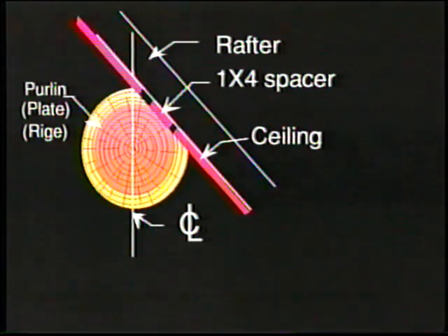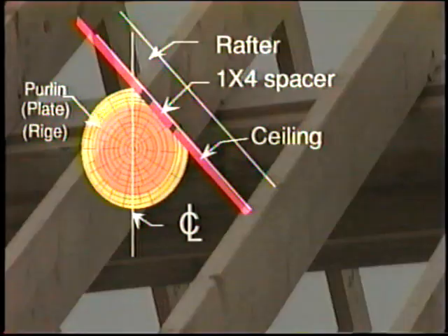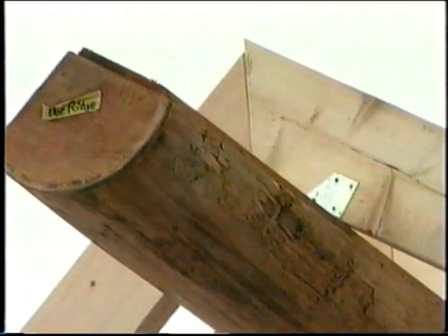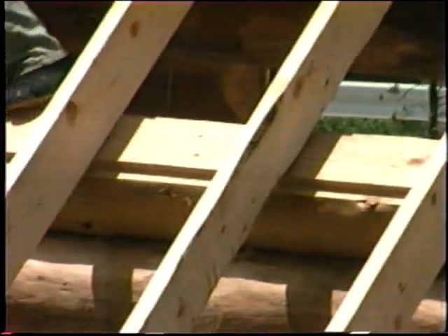In preparation for the common rafters, nail a strip of wood, 1x4, to the top of the plate, purlin, and ridge logs that will lift the rafter the thickness of the ceiling material. This will greatly speed up and improve the quality of the ceiling application. Alternately, this step might be rabbeted into the beam before it is put in place. This will be a little stronger, but a lot more work.